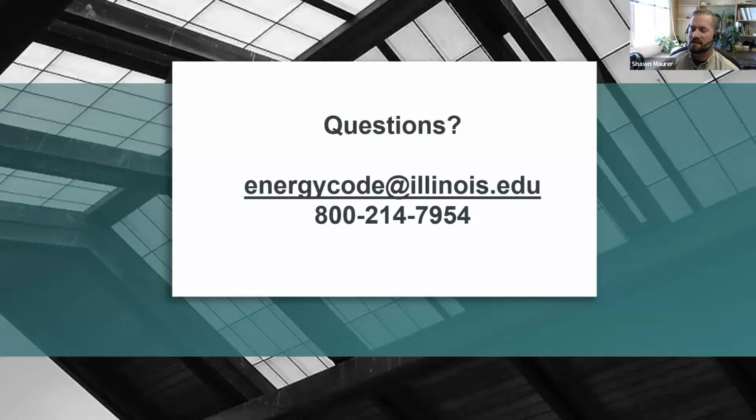As far as the heating and cooling systems, though, ComCheck really doesn't do a percent beyond code check there. It's only for lighting and envelope. On the heating and cooling side, it's more of a checklist, making sure that your fan efficiencies properly meet the requirements in the HVAC section as far as fan efficacy and efficiency. And then it's checklist items to make sure that the rest of the HVAC is accounted for.